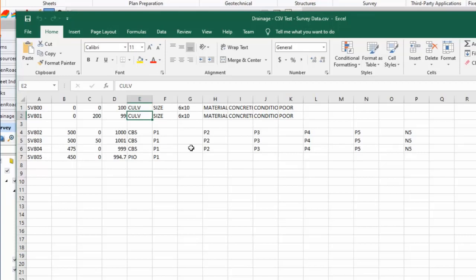Now notice for this culvert, I'm not using a begin line or inline mapping code. It uses just the points that are stored when the survey data is processed, and our CSV file will define how these points are connected. I also have points for a catch basin square, 3 of those, and a pipe inlet or outlet point. On each of these they have attributes, but in this case none of the attributes have values. So our CSV processing does not read any of these attributes. We'll have to define the size, material, and dip information in our CSV file. So let's take a look at that CSV file.